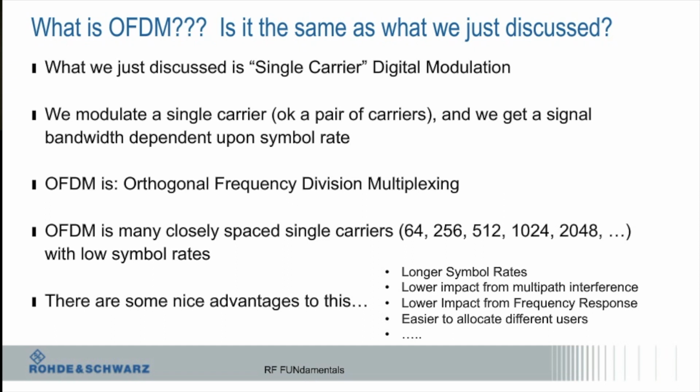IQ scheme, where I took one and I put it in quadrature. But that's shifting phase by 90 degrees. Right. This is doing a different frequency, right? Yes. But I can do a lot of that digitally, right? So I can put an offset frequency into my baseband signal. I put an offset frequency into it. There's different means of doing it, but it's a good question.